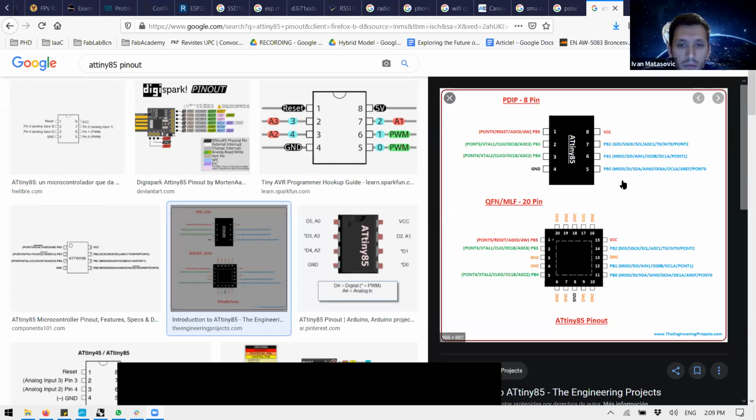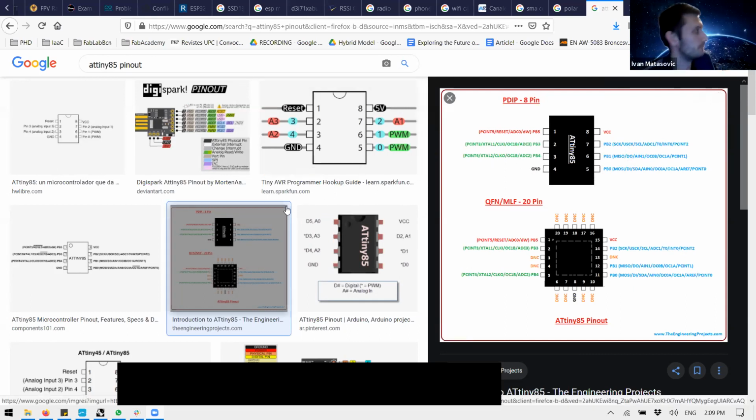For example, the ATtiny families, you program them through SPI. They have that connection. And I2C is really like the two basic connections that all the microcontrollers have. Most of the microcontrollers, for example the Tiny family, don't have a serial. Yeah, soft serial, and I need to use soft serial. Okay. Thank you.